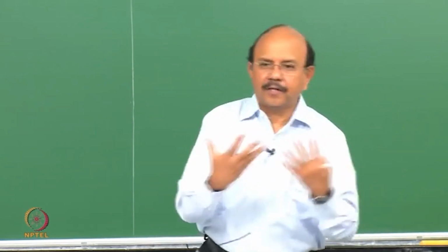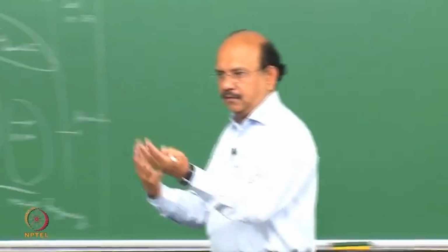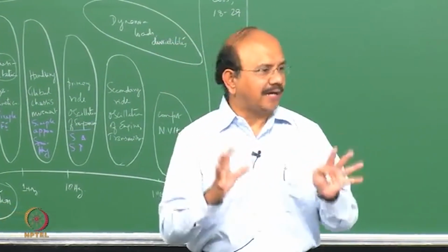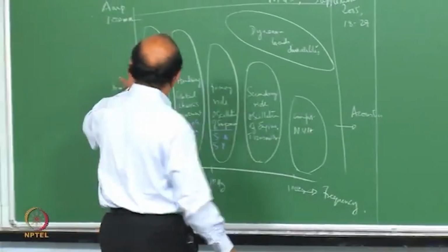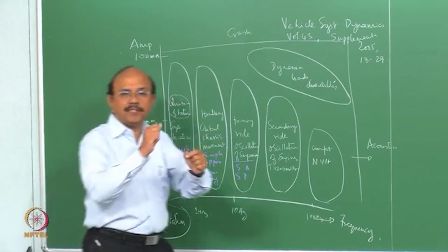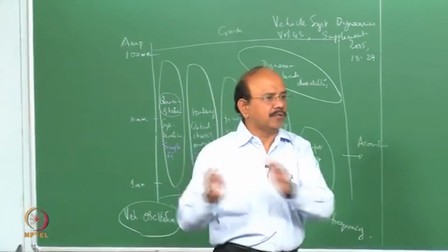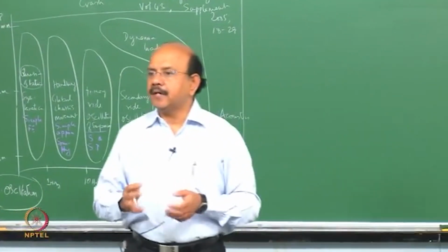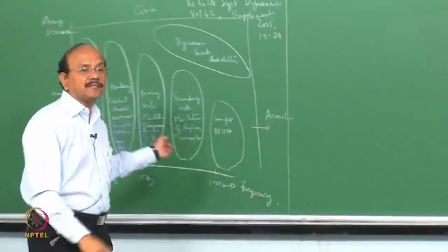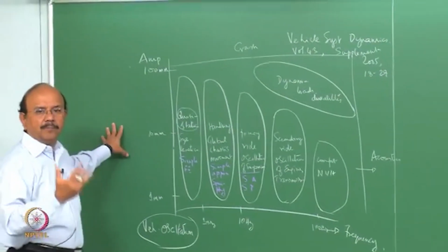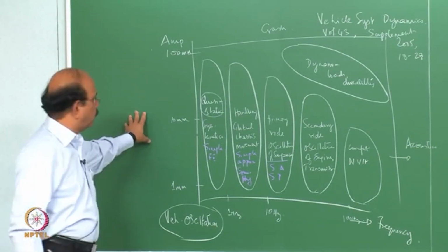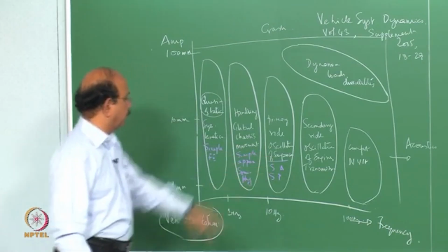You use the fundamental concepts in theory of machines or kinematics of machinery which you studied in order to understand that. So those are the quasi-static models, right? The amplitudes may be very large because you're looking at how things move when you turn the steering. And many times the model that you use for a tire, in this case, is a simple static finite element model and so on, right? We'll come to these tire models in a minute.